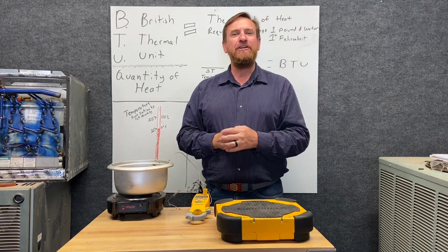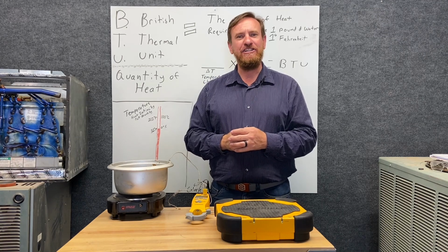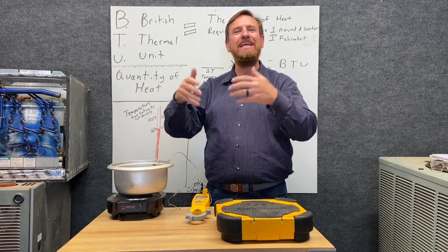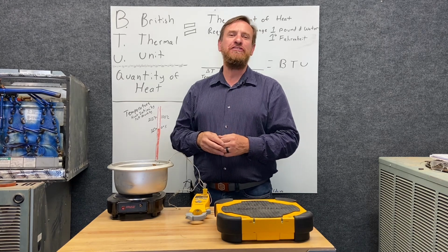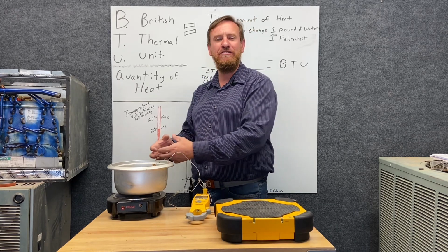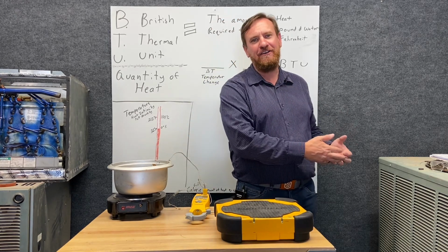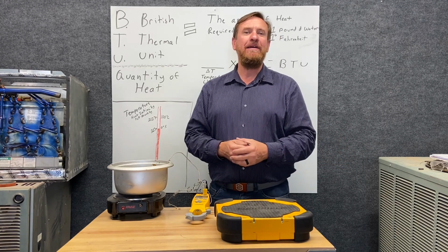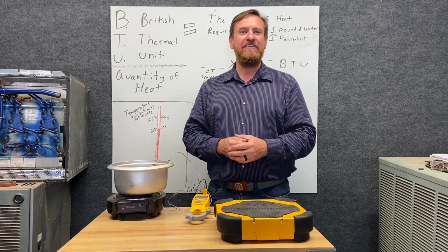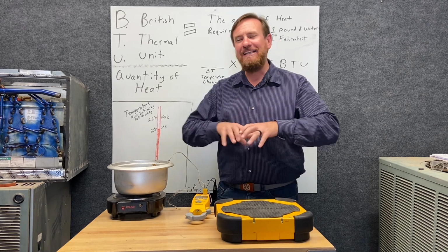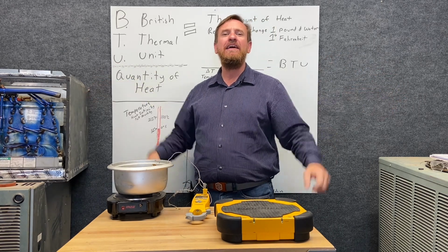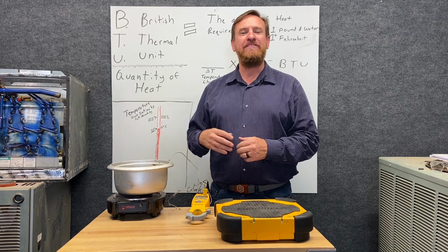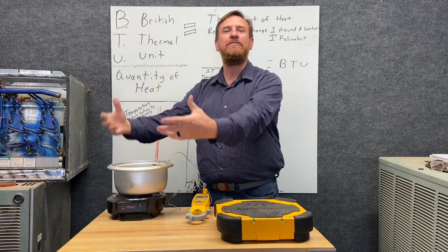So in the summertime, we're going to do BTU heat load calculations. How much heat in BTUs is coming into the house? And our air conditioner needs to be sized in BTUs, how much BTU energy it needs to take the heat out of the house in the summertime. And in the wintertime, how much BTU the house has lost, a heat loss calculation. So BTU is going to be leaving the house, going to the air outside, and we need to size our furnace or heat pump to see how many BTUs of heat we need to replace or put back into the house.